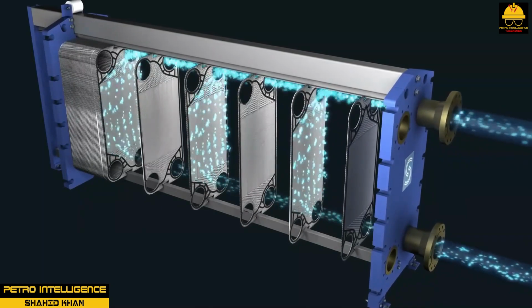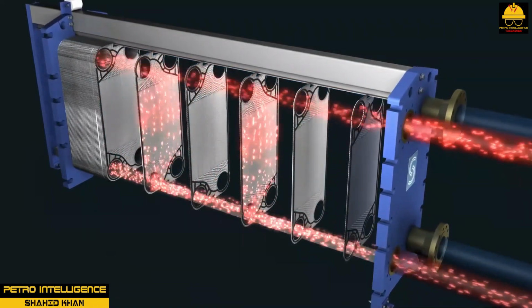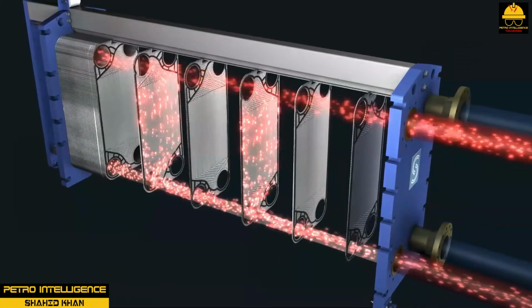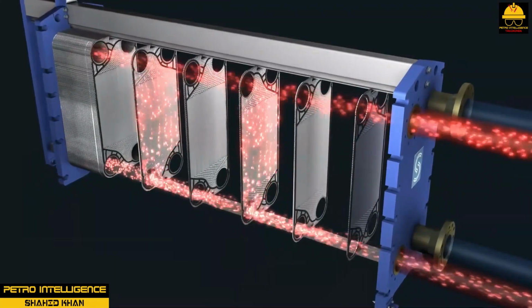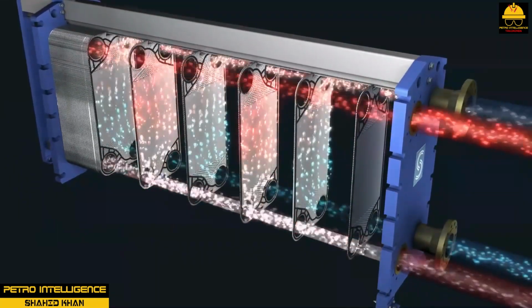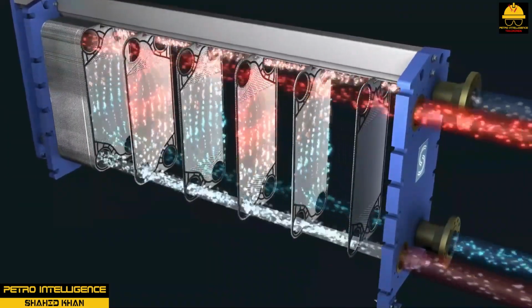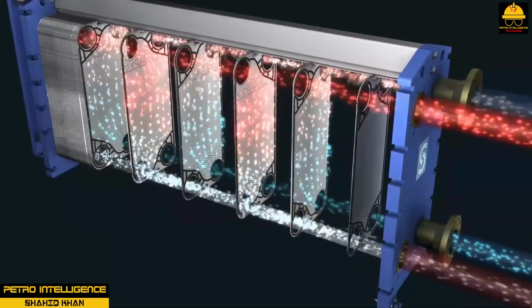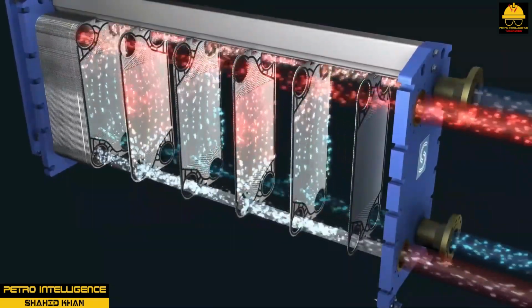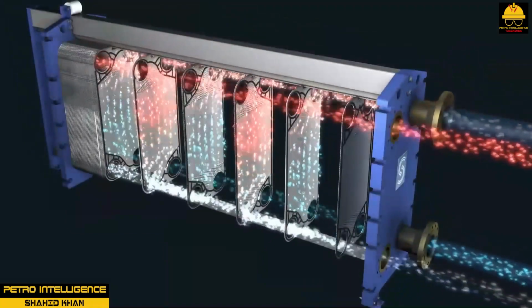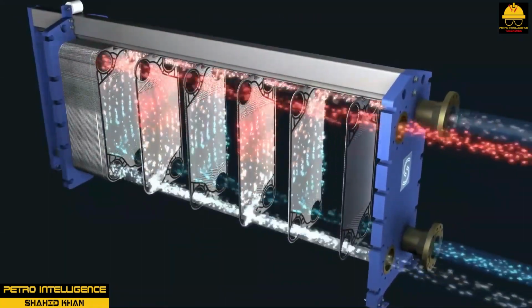The plates are designed with an alternating series of chambers. Heat energy is transferred through the walls of the plates by conduction and into the liquid by convection. The hot and cold inlet lines run the entire length of the plate heater and function like a distribution header. The hot and cold collection headers run parallel and on the opposite side of the plates from each other.